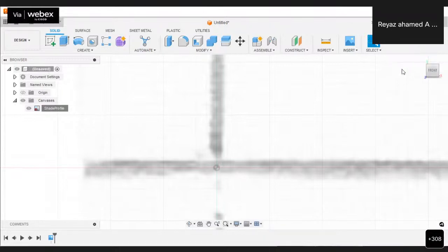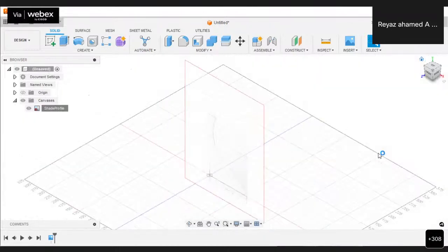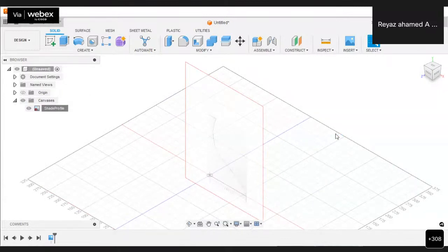And then rotate the view cube to home view. See, now the object's length is converted into 135 mm, and also the same image is brought to the origin of our Fusion 360. So this image is going to be converted into a solid part model. Like this, you can also create any sketch on your paper and then click a picture of that paper with your drawing. Then you bring your drawing into Fusion 360 like what I have done so far.